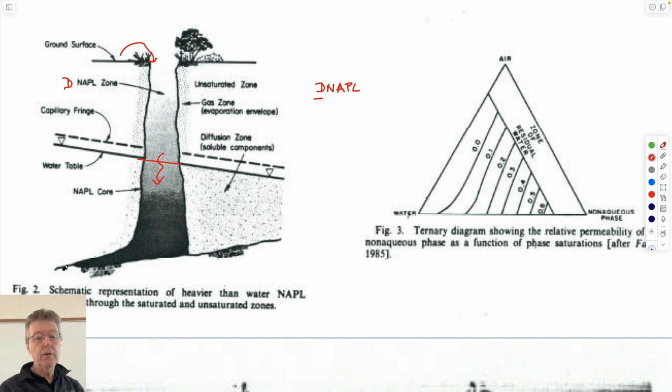The equivalent of that for an aquifer would be a layer which doesn't allow it to cross. So this would be a layer where the hydraulic conductivity or the permeability is sufficiently low, not zero, not infinity. And so this will act as the bottom of the swimming pool. And so these will just scoot on down. They'll pond at the base, so they might look like a puddle that's present at the base. It can't go anywhere. It could roll down this interface if it existed, probably won't. And it also will leave a smear as it goes down through here.